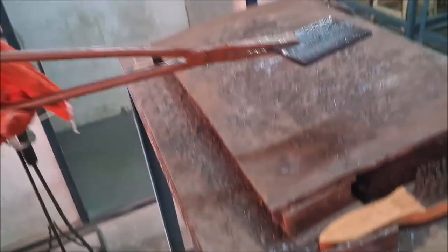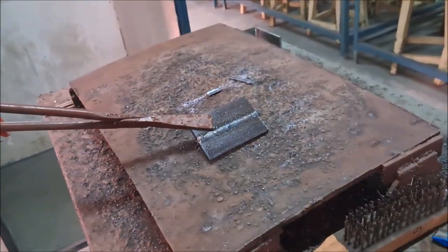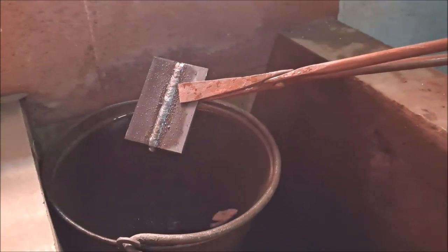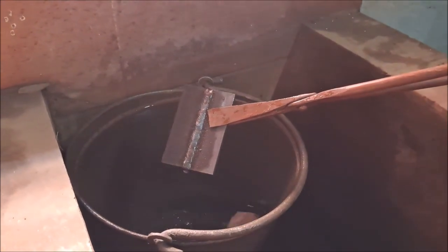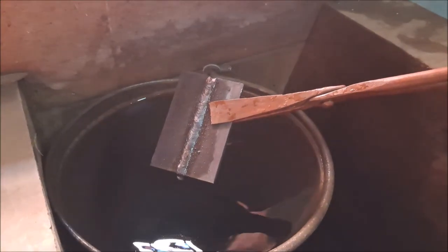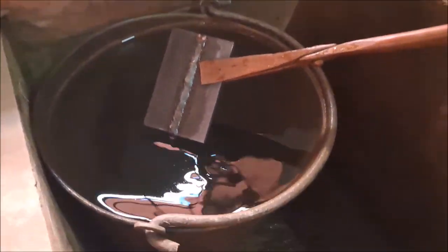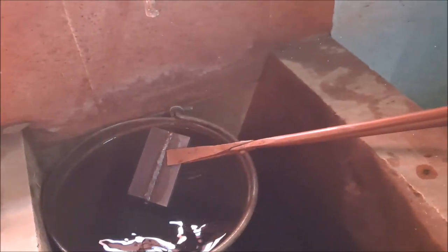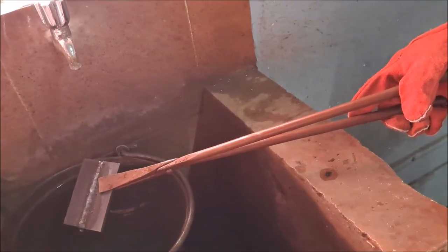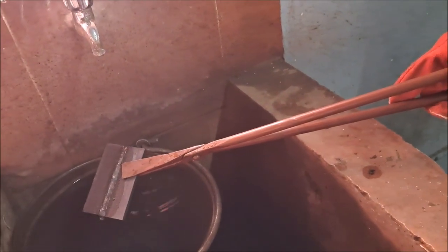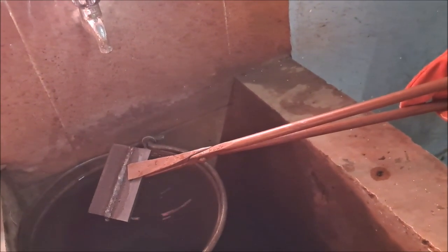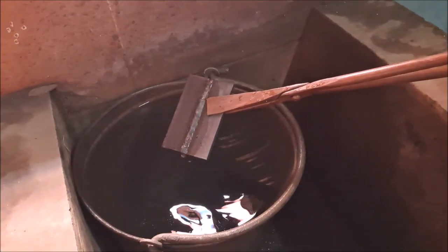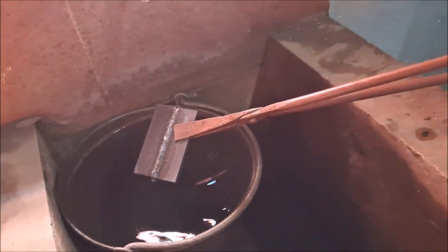see that after completing your welding process, don't directly dip it in the water. This is not the right way, because it is still in the steady process, so if you directly dip it in water, in industries we let the welded part cool in the atmosphere only. If you directly dip it, your welding will not be properly welded. Your welding will be broken. So this is only for your safety purpose, to dip in the water. In industry, we do not do like this.